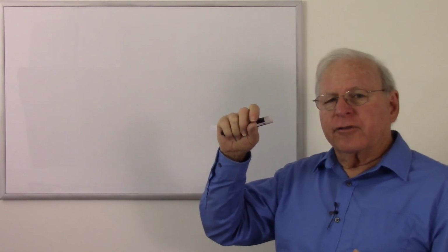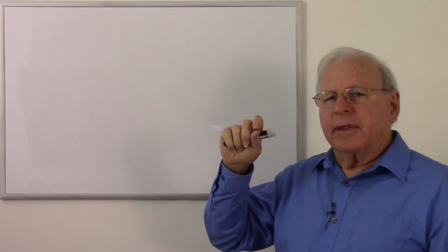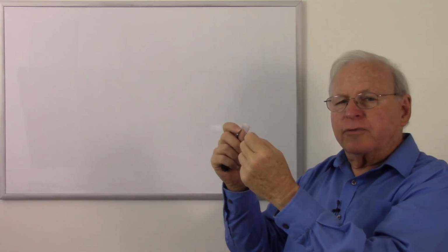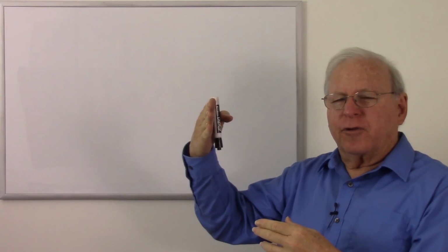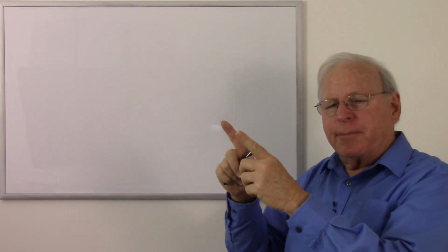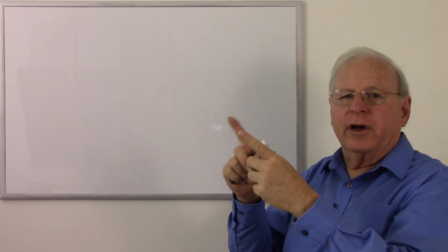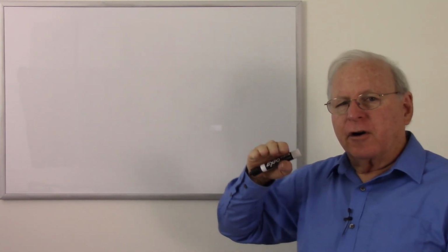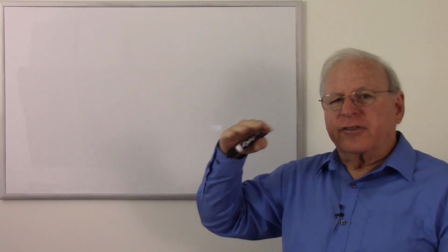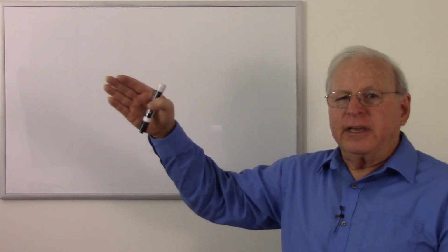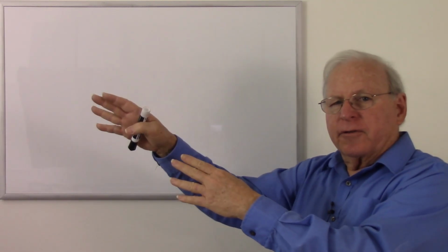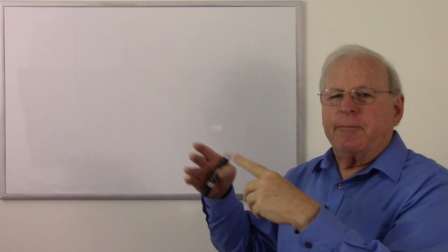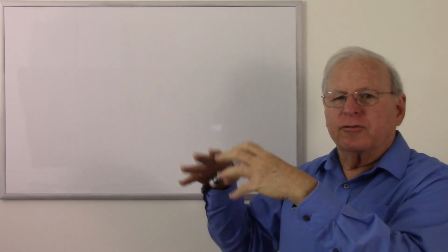And so they have speakers where we have a transformer that connects the speaker to the voltage rating. So we have an 8 ohm speaker with a transformer attached to it, and there will be tap-offs for like a 70 volt system or 100 volt systems, and you tap that off and the amplifier will amplify to the same voltage regardless of the impedance out there on those speakers. Because as you know, if you put speakers in series, your impedance will go up. If you put them in parallel, your impedance goes down. So we have to deal with that.